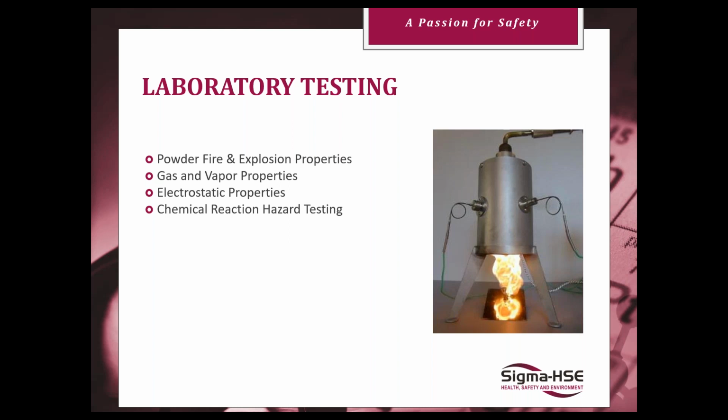And as many of you will know, risk is a function of the consequences of a hazard, the harm that hazard could do, and the likelihood that that harm will actually be realised. So therefore it goes without saying, really, that identification of a hazard is the key step. If we miss a hazard, if we forget there's a hazard present, we won't then consider measures, barriers, safeguards to protect ourselves in our process designs.